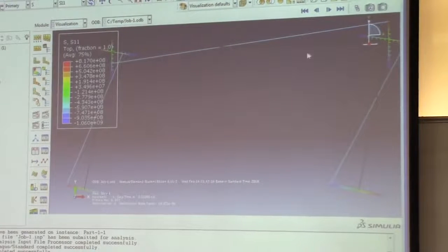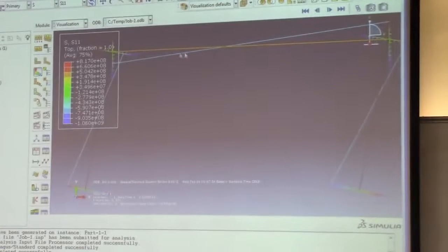Because these two beams are only subject to concentrated force. And for concentrated force, the beam element type in Abaqus can give you accurate results. So one element is good enough. But for this beam, because it has concentrated force and distributed force at the same time, and Abaqus can only do the approximation, if you use just one element, the result is not accurate.